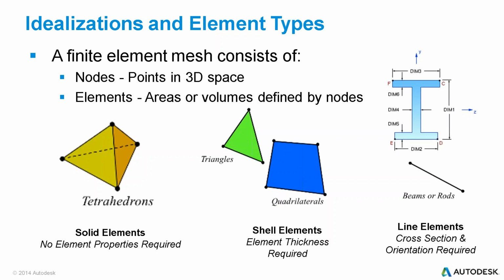So when you're looking at something like a solid model, the amount of tetrahedrons you have is going to determine how accurate those results are. If it's too few, then you may not be getting enough information. If it's too many, you could be getting some stress risers that you may not even encounter. The benefit of using a shell element is it is a simplified representation of your model. So shell elements are used heavily on sheet metal type designs because you can make some assumptions and you work with a midplane. That midplane will reflect the inner and outer face conditions of that sheet metal shape.